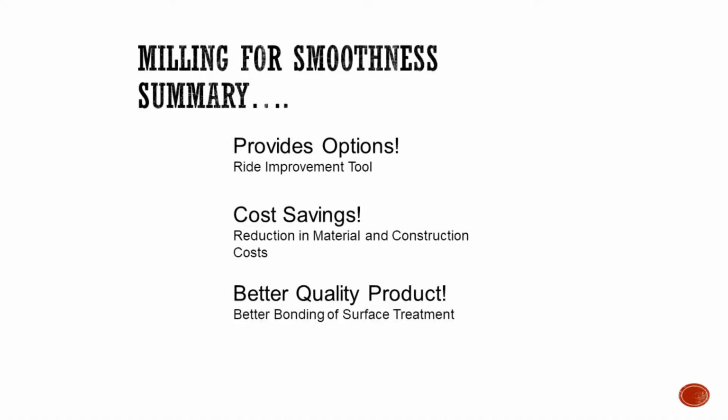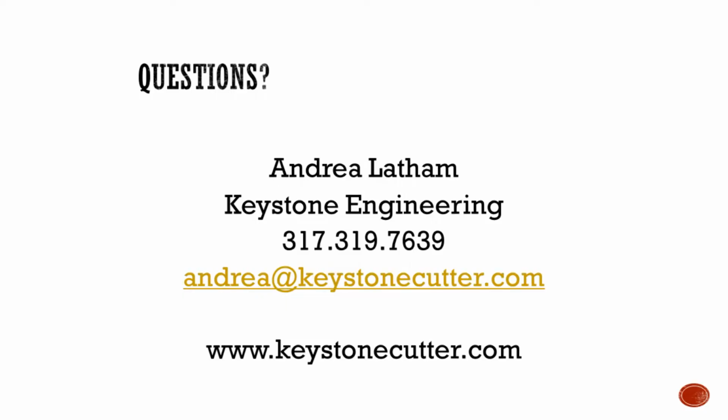There's the process, whether it be micro milling or flat tooth milling, it brings us so many different options. Roads that traditionally we would probably say, hey, look, no way, this is going to need a mill and fill, but it really opens up those jobs to preservation treatments, and therefore saving millions of dollars in certain cases and stretching those funds a little bit further. And in the end, you're going to end up with a better quality product, doing it before any surface treatment, really, to get that adhesion and everything else, the benefits that you see, not just the ride quality improvement aspect. At this point, I'd like to open up the floor to any questions.